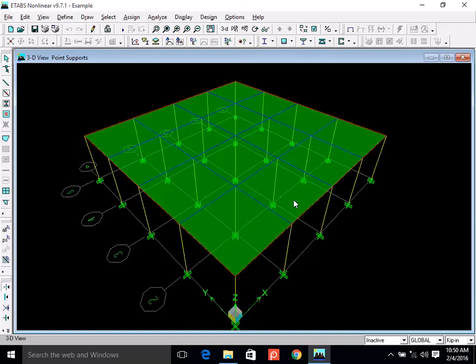For example, you look at the architectural drawing of a school and you see that there are some classrooms. You need to write on your plan what is the live load for the classroom. Then there are corridors. You need to write on the drawing what is the loading for the corridor. There is a staircase, what is the loading for the stairs? And if it is a laboratory, a store, any occupancy. So based on occupancy, you have to know what is the probable live load. And where do you get it from?